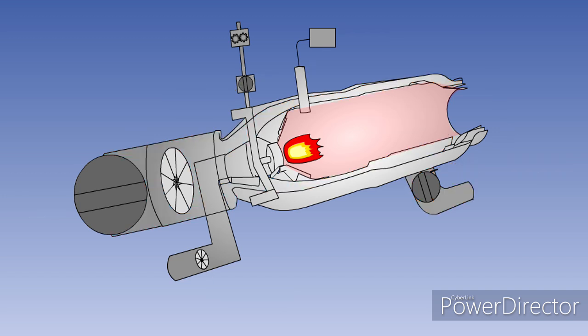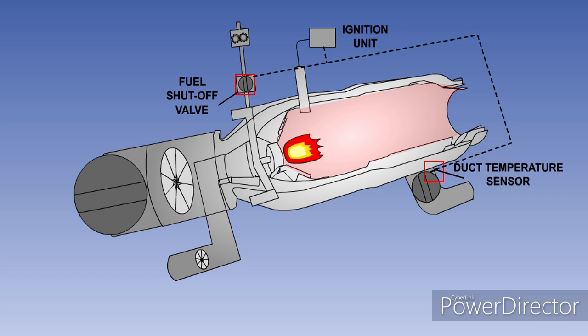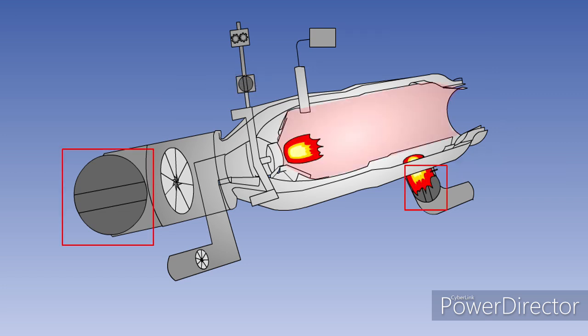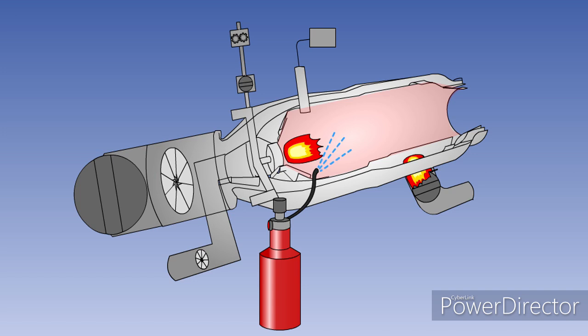The combustion heater is provided with a number of safety devices, which will include an automatic shut-off if the outlet air temperature becomes too hot, and adequate fire protection in the event of failure of the structural integrity of the combustion chamber. This will normally be a system for shutting off the fuel and sealing the air ducts if flames enter them. An automatically operated fire extinguisher is also incorporated in some systems.